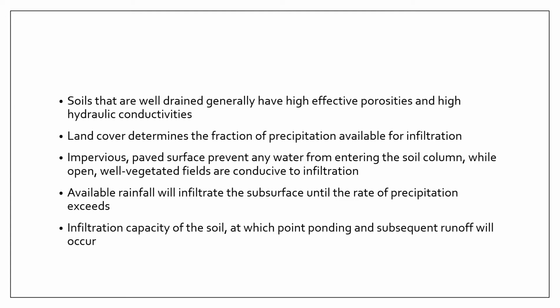Right now for soils, in general, your well-drained soils like sands and gravels have high effective porosities and high hydraulic conductivities, meaning they are able to transmit water fast, and they're also able to store a lot of water.